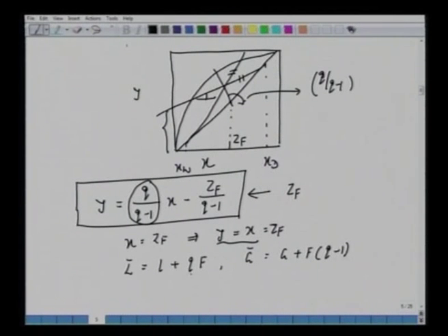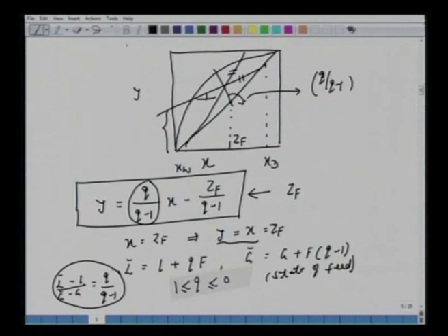So, all right, Q can take any values between 0 and 1. That's why it's called quality, the state of the feed. It decides the state of the feed. And from this, if you divide, then you should be able to get L bar minus L over G bar minus G, so that this is your Q over Q minus 1, the slope of this Q line.